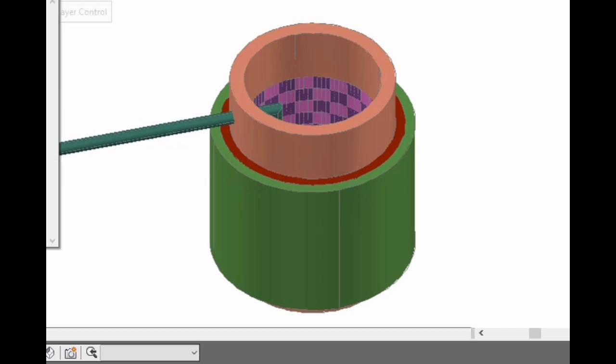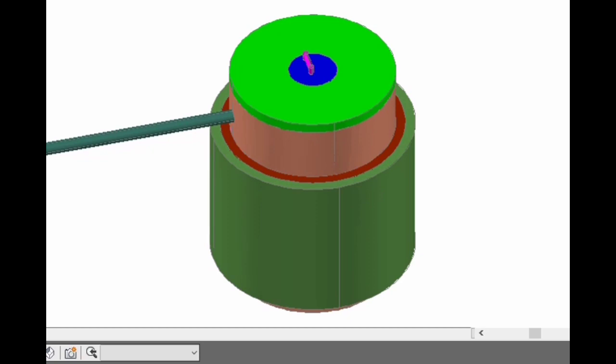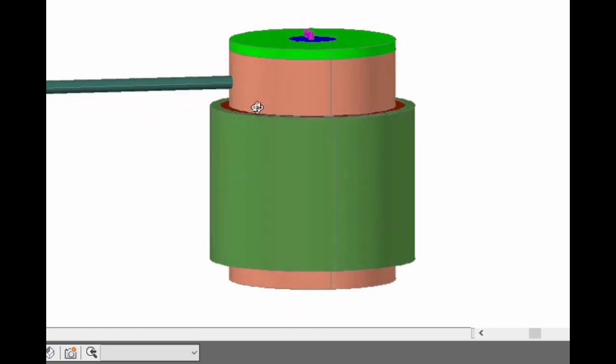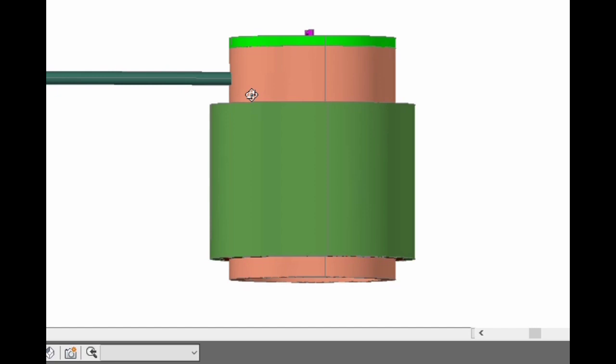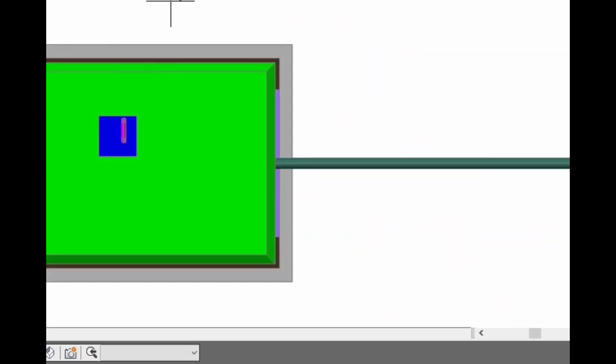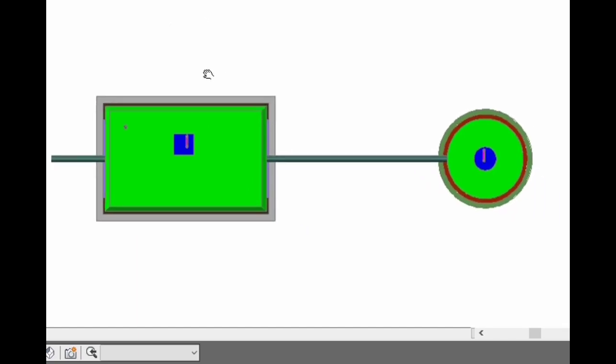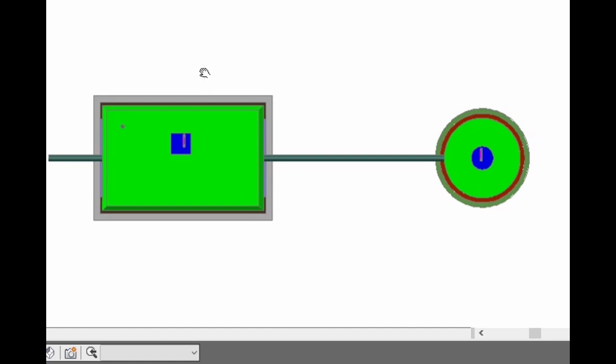Over this you are going to place the slab and the cover for that. Like this it will be covered. All this will be embedded in the earth. Completely you are going to bury this and the septic tank under the earth. Now let us have the longitudinal elevation of this one. Now what you are seeing is the top view. It is a top view of the complete structure, the septic tank along with the soak pit. I am going to cut it along the central line of this pipe.